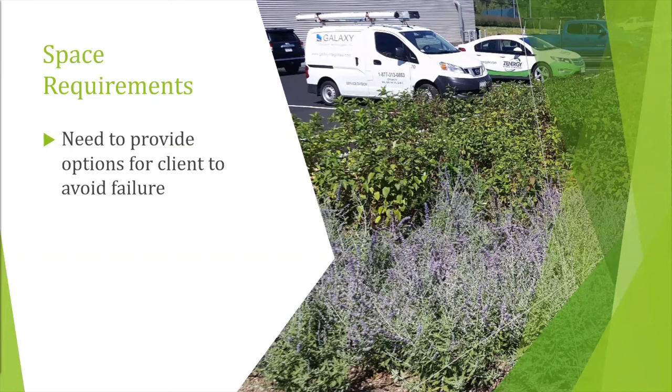So again, always walk through those benefits with a client, because a lot of times people throw in a closed system, an underground structure. I should mention that underground water quality structures are like media filters. It's a large vault that has a turbine to clean it. But again, it requires a lot of maintenance because it is an underground structure, versus a natural system like this, which really just does the filtration through the soil system.